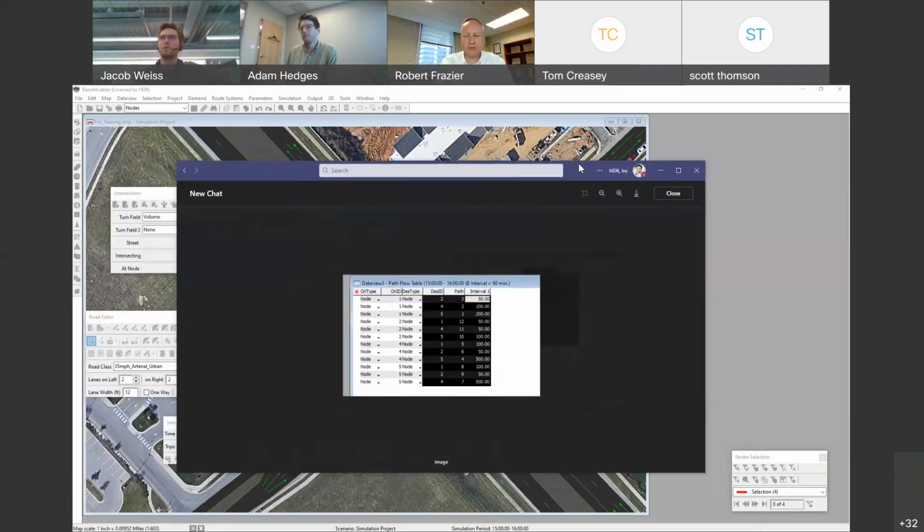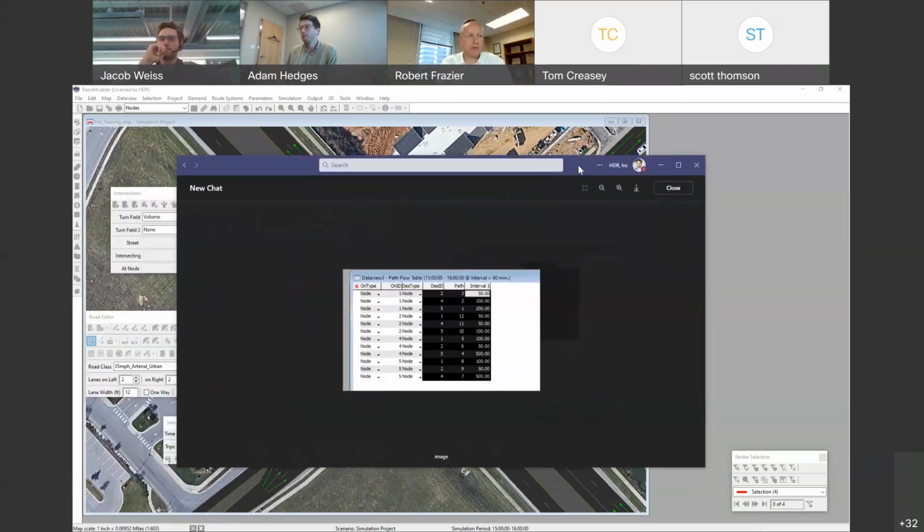Plus, an OD matrix will allow you to quantify the actual demand. If you're over capacity and you have a count at an intersection, then basically you're just counting the saturation flow rate and not the demand. So you would actually not capture the demand as an input to the simulation.